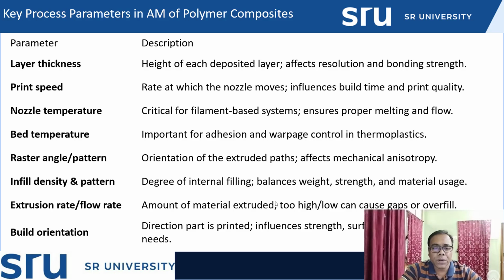Similarly, coming to the extrusion rate and the flow rate. Extrusion rate is nothing but the amount of material which is extruded or coming out from the nozzle. If the amount of extrusion is more, more quantity of material will be coming and will be deposited. Too high or too low can cause gaps and overfill or underfill of the material. So that's why one has to avoid certain kinds of parameter selection.